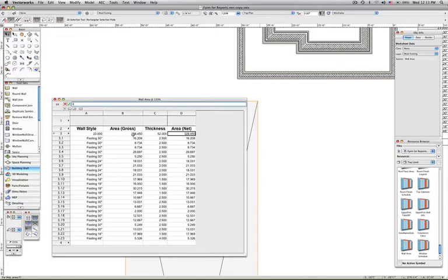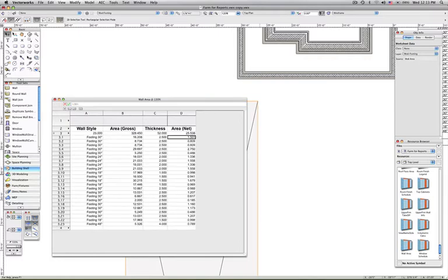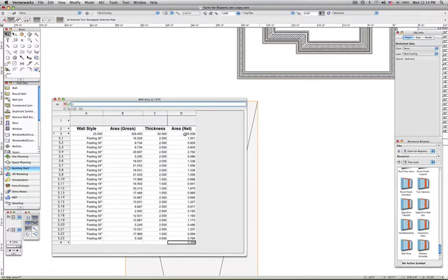So I'll just reuse the column area net and move it and type in a formula to calculate cubic yards. I'll need to write a little equation that converts cubic feet to cubic yards, and then, with a few formatting touches, we have a table that calculates the number of yards of concrete in the footings. Okay, I like it.